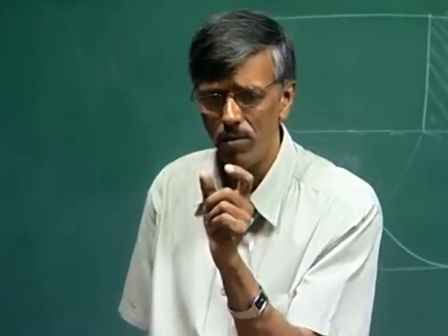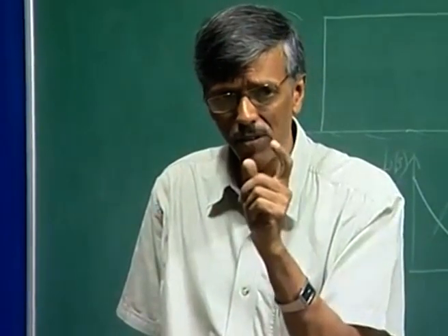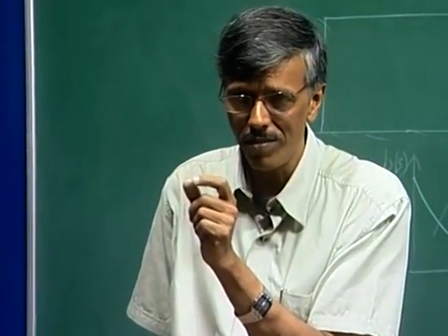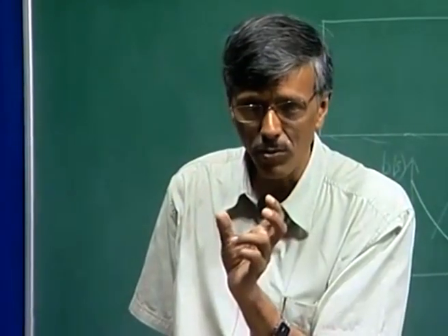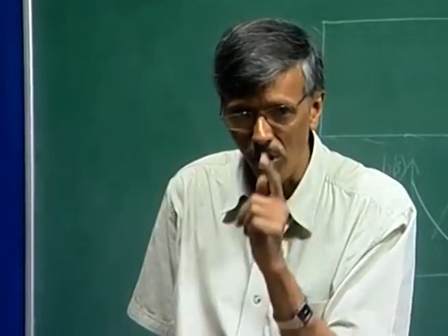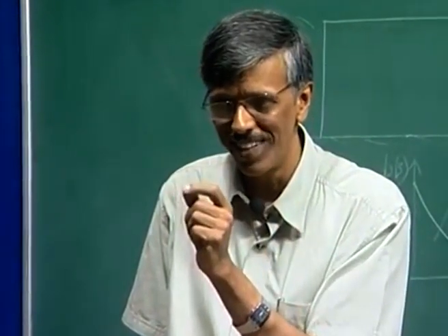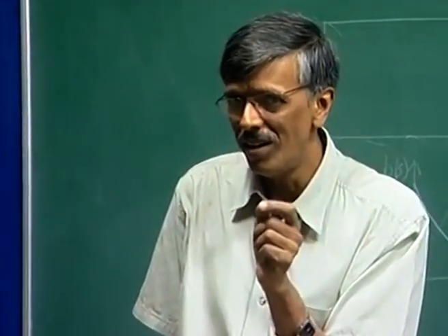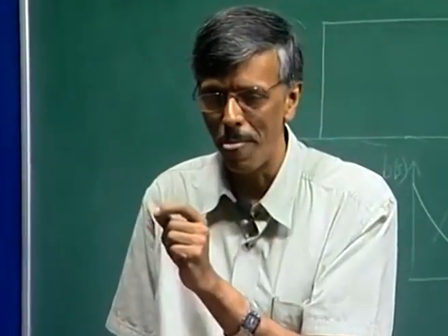So, I will show you a few days later what happens when we excite a boundary layer with a strip that may be still going at a single frequency, but because of this finite width I would create waves of different wavelength. Why? Because of the finite width, my local Re delta star is also not a single number, it is a band. So, each point works as a source, and each point, because they have a different Re delta star for the same omega naught, will create different alpha r and different alpha i, and I have to sum it all up.